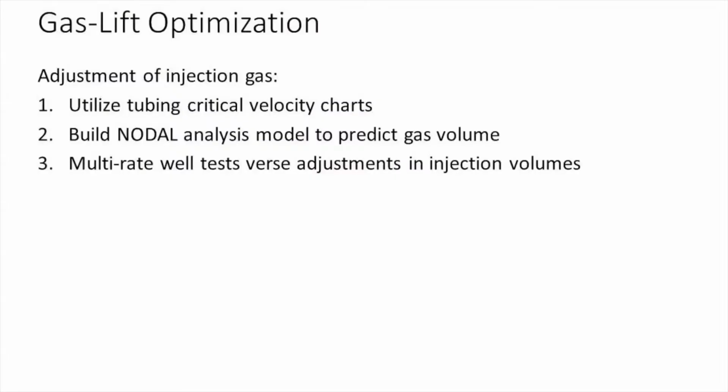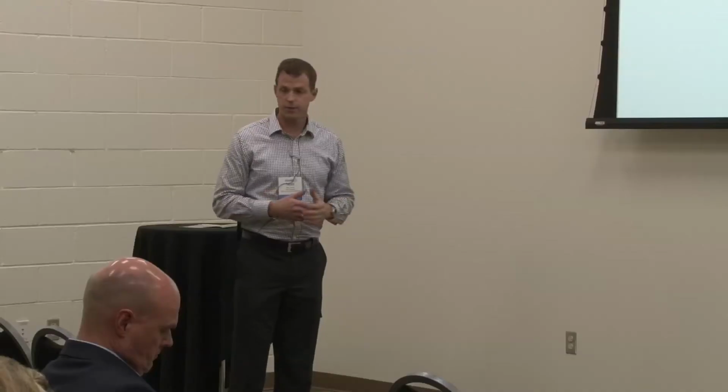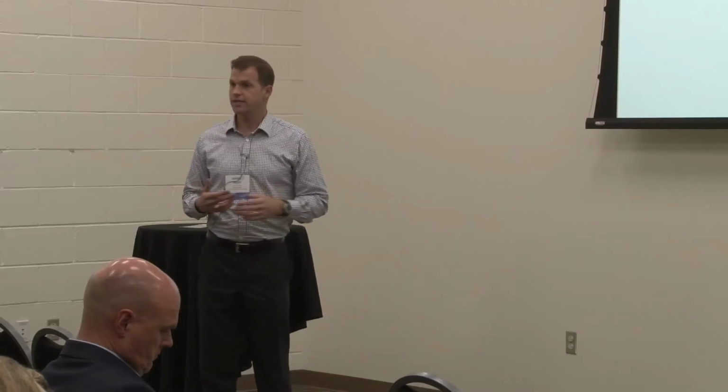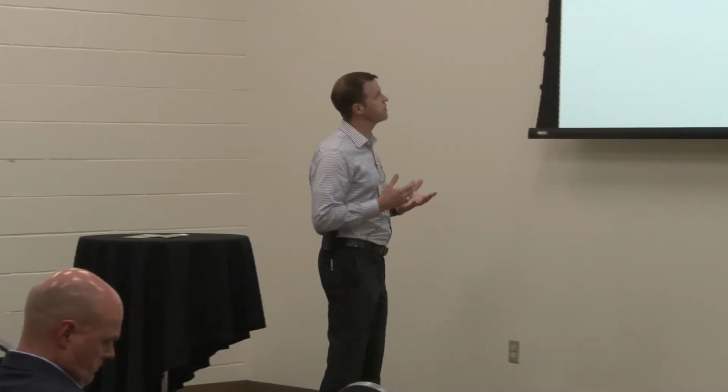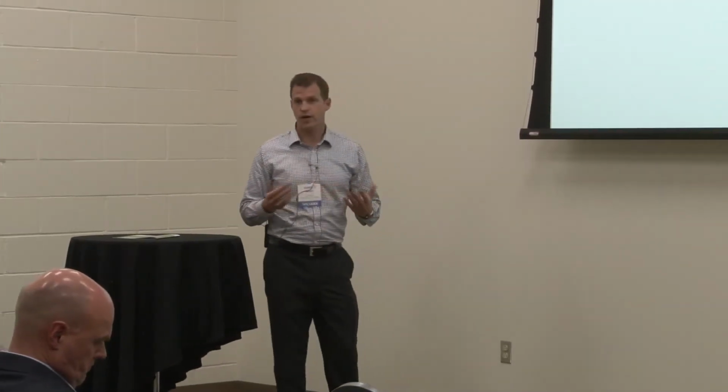So when we look at adjusting injection gas, there's really 3 main avenues that adjusting injection gas is taking place. More times than not, number 3 is the most common. We make an adjustment, we watch the well test, we make an adjustment again. It works, it's very time consuming, it's very manual, but it does get you to the point.